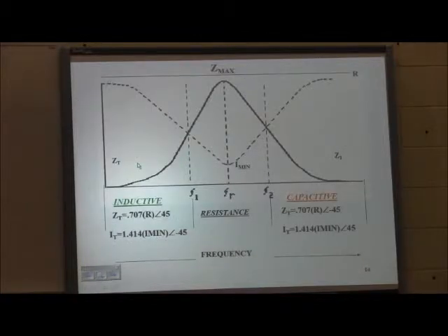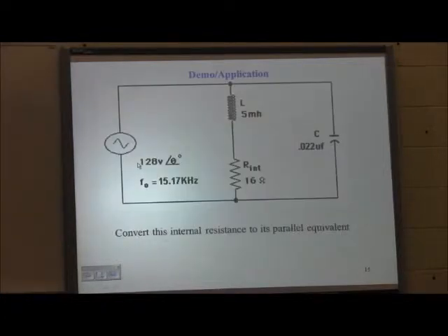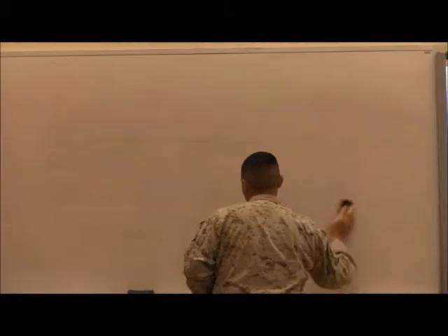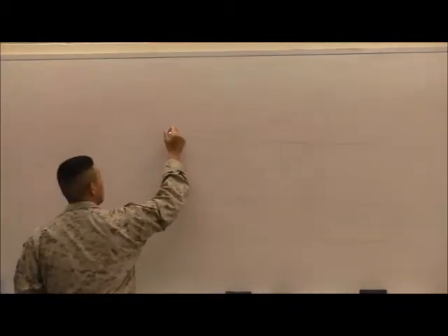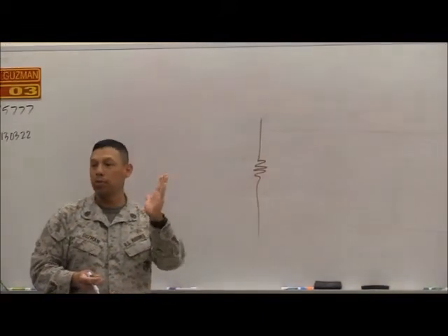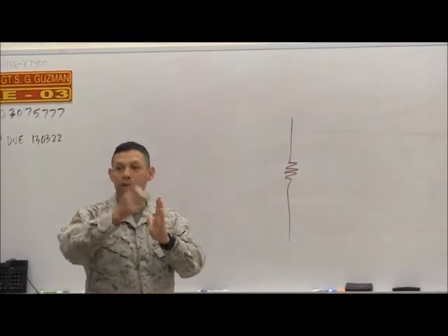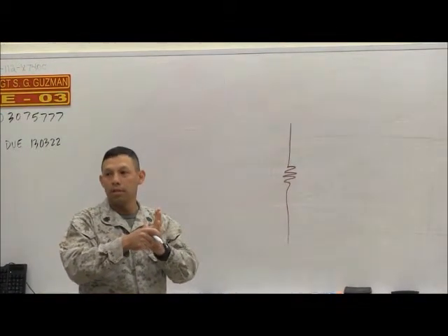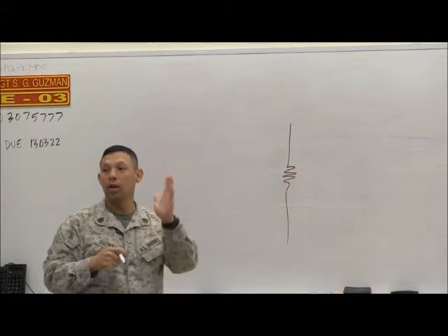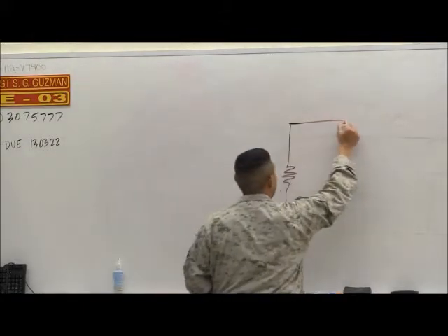All right. Well, we said that at F1 in series, it was acting capacitively because X sub C was bigger. Right? Because at F1, you're coming from 0 hertz going towards the frequency of resonance. So you're still at the lower end of the band. So the inductor is more of a short than the capacitor is at the low frequencies. Okay. So, but in parallel,